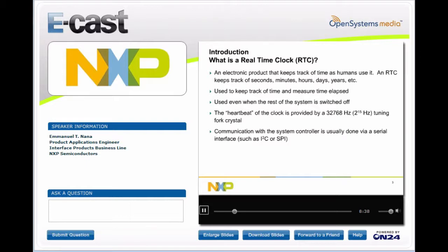The watchdog function basically provides an additional safe bet for the system. So if in case the microcontroller locks up and the watchdog within the microcontroller is also locked up, then the watchdog within the real-time clock can still wake the system and recover it from any failure that occurs. Then the additional power management features just help to eliminate additional components within the system. So some real-time clocks do have power management features that can be done within the real-time clock, and so that saves on additional components on the board.